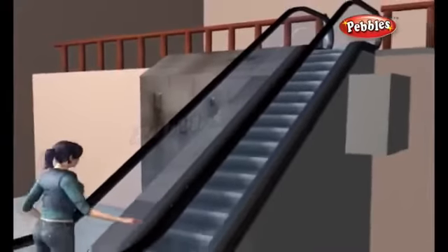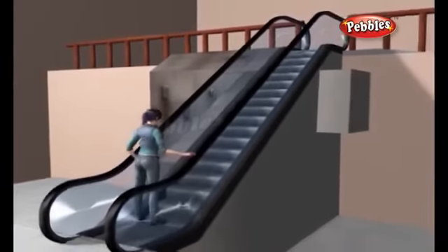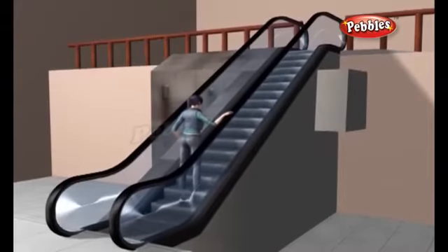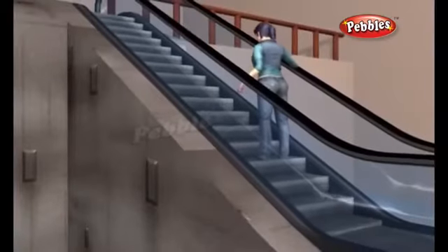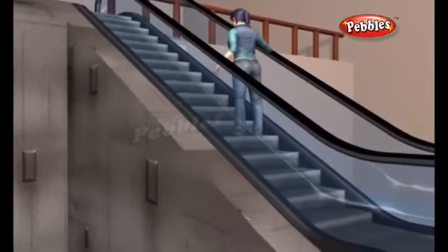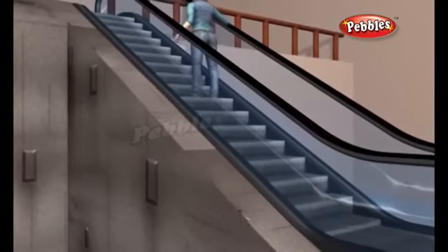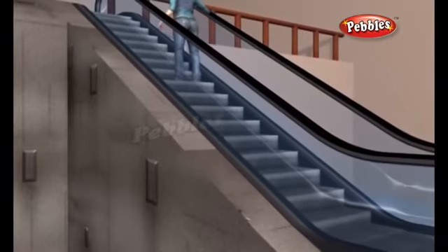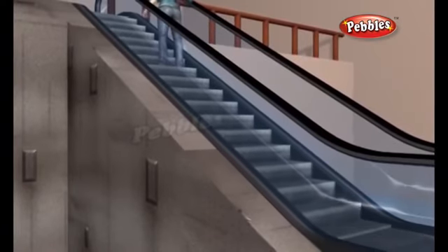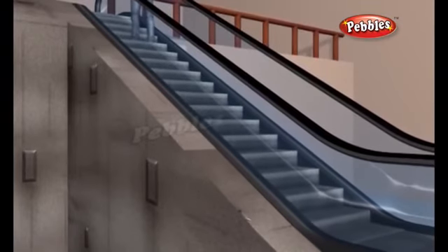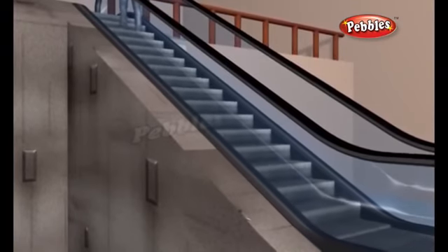The escalator system isn't nearly as good as an elevator at lifting people dozens of stories, but it is much better at moving people a short distance. This is because of the escalator's high loading rate. Once an elevator is filled up, you have to wait for it to reach its floor and return before anybody else can get on. On an escalator, as soon as you load one person on, there's space for another.